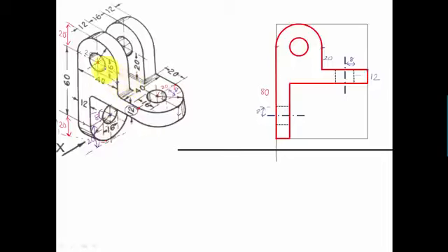Let me try to do that. Like this edge you see over here, similarly there is an edge behind, something behind the surface. Let me try to make that. It's going to look something like this. There is an edge going to be behind. Now this edge cannot be seen directly, but it has to be given some respect since it has its presence, and that can only be done with the help of a hidden line. So from over here till here, in a very horizontal way, we're going to be drawing hidden lines. There you go. So the front view is almost done.